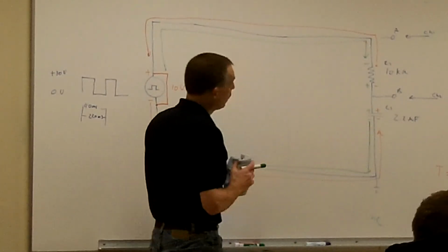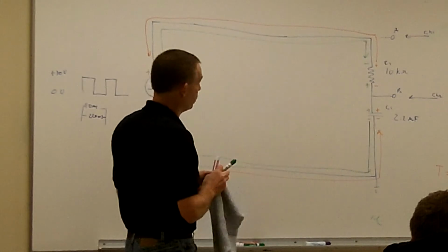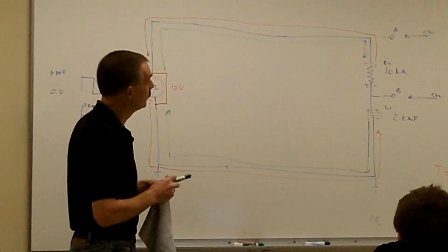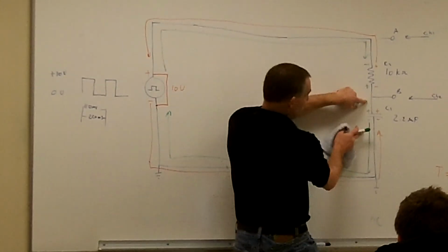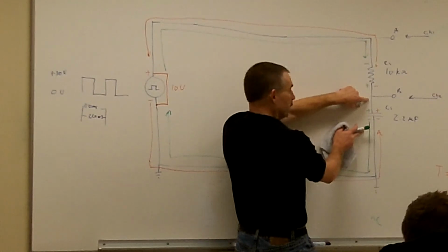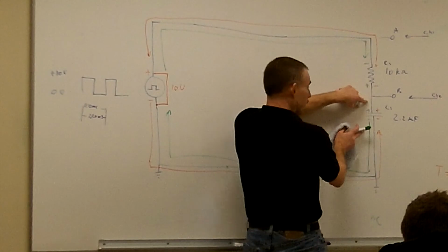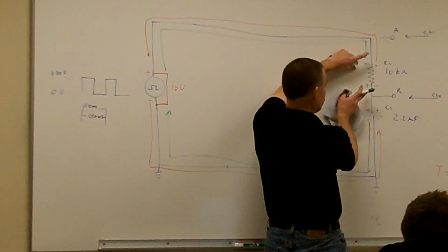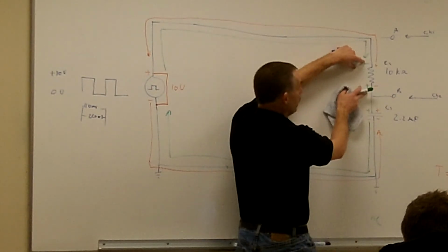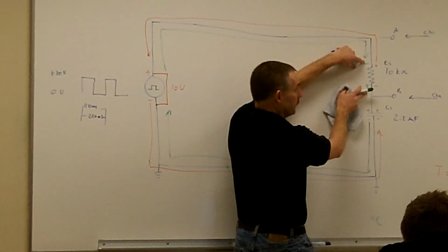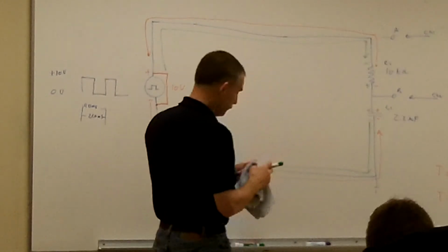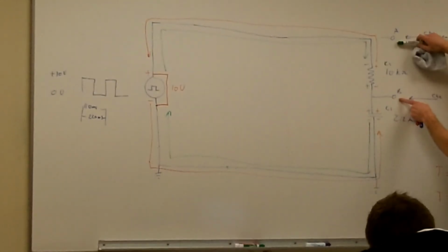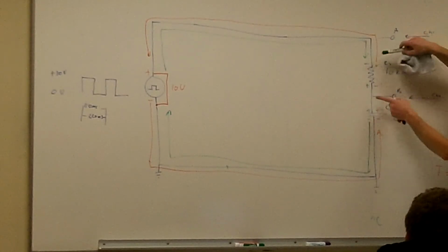What's my voltage across my resistor going to be? Here my capacitor becomes my source now, and it's charged up to how many volts? 10 volts. So that's my source. Once that transition from a positive 10 to 0, the current starts flowing. What would I have for voltage across the resistor then? 10 volts. Before, on the first alternation, it was positive-negative. Now it's going to be negative-positive.